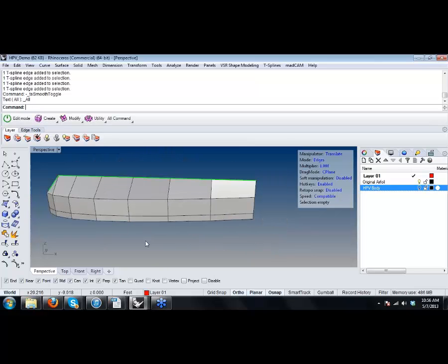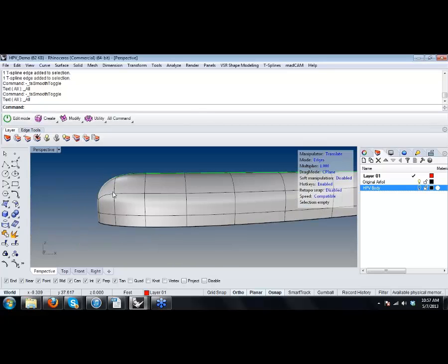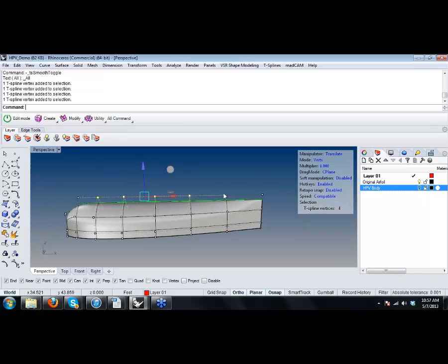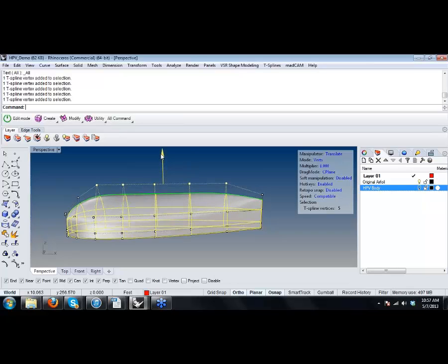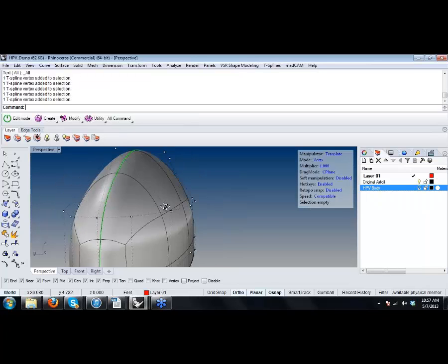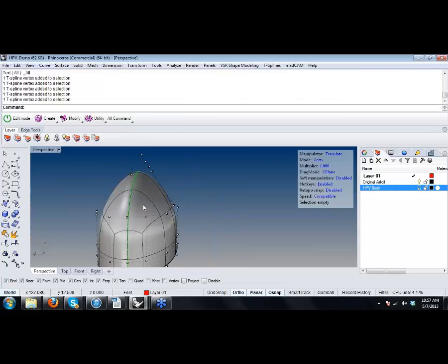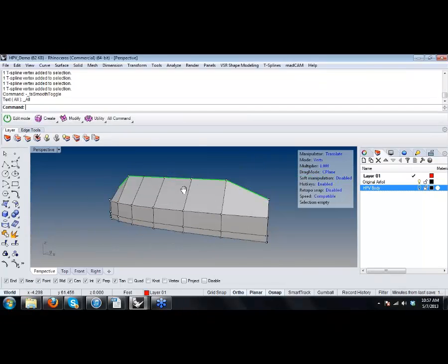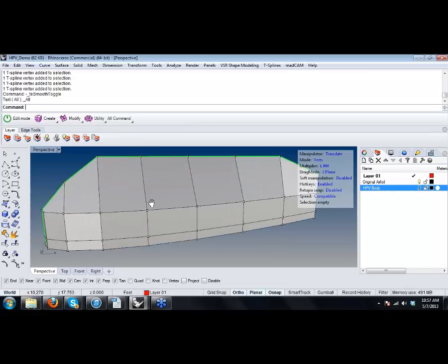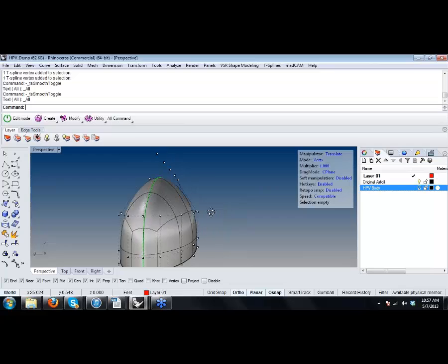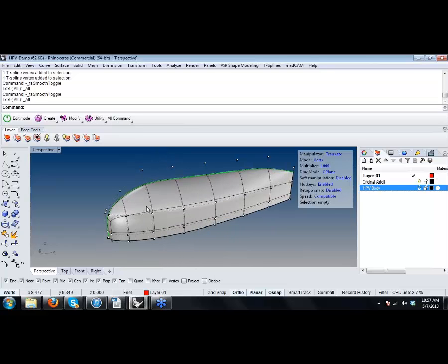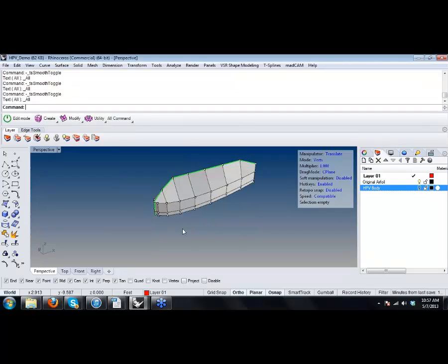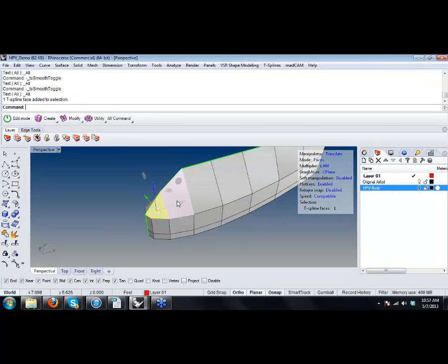Okay. So you can start to grab these verts to create this roof line that Kyle has. Now, you may also think about how much control you want along this line here. The way I have this set up, I don't have any lines or verts running along here. And looking at it, when I switch this into smooth mode, I realize I probably want that. There's not quite enough control along here to control the arch shape of that ridge line. Let me show you a really quick and easy way to do it.